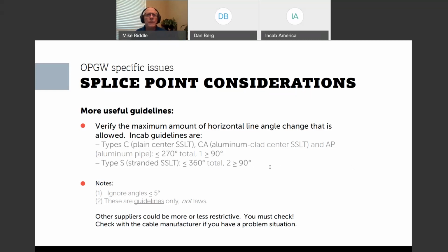If a contractor is involved, they can argue that, well, you gave me the cable and something happened during transportation. I don't care that it was good when it left the factory because the supplier gave you this test report. Something happened during transportation. Of course, the truth is nothing can happen that wouldn't have some obvious sign of physical damage to the cable that would affect the optics. But you take that out of the equation if you do a test.